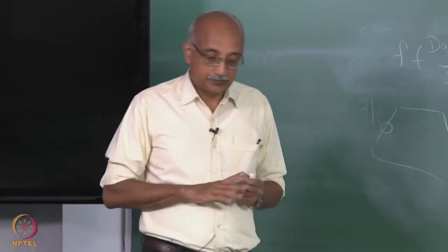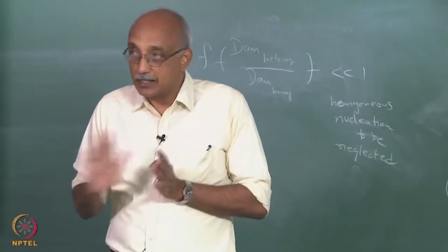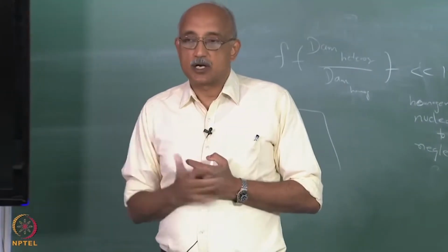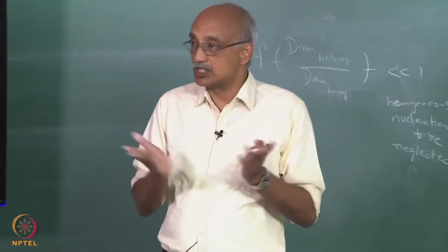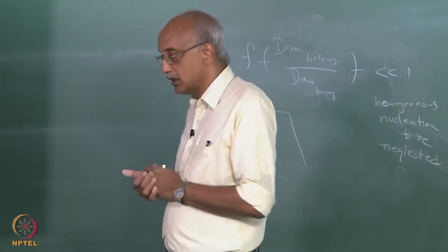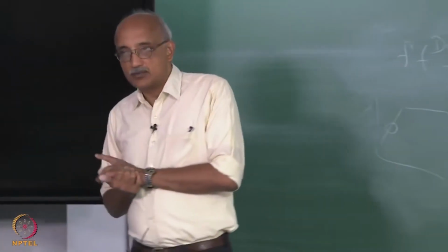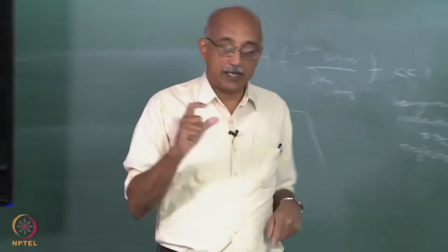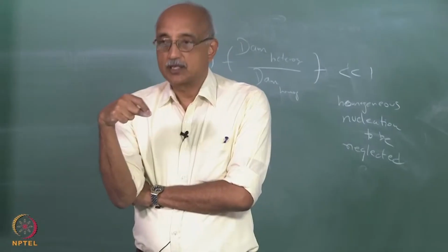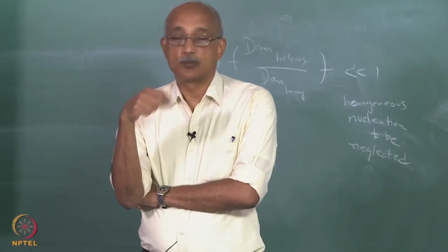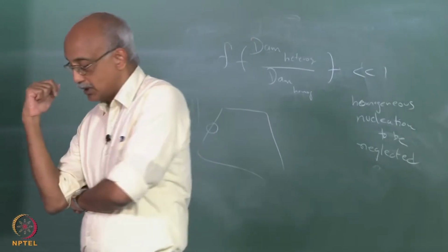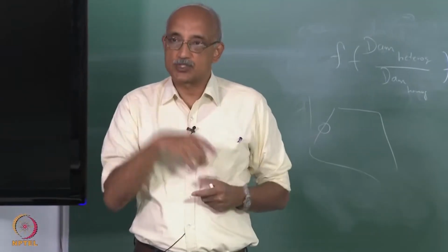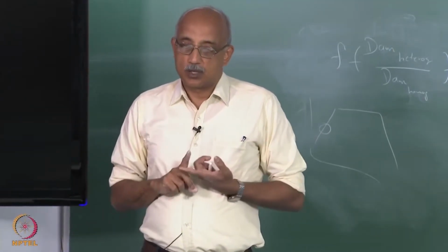So, what that implies is thermophoresis is always acting against you if you are trying to deposit aerosols, because the aerosols will be rejected by the hot substrate and driven towards the cold walls of the chamber. And that is one reason why aerosol CVD reactors are very difficult to design and operate, because thermophoresis, which can actually be orders of magnitude stronger transport mechanism compared to the Fick diffusion or Brownian diffusion in the case of particles, can really result in a net depletion away from the substrate rather than a deposition on the substrate. So, how do you handle that?